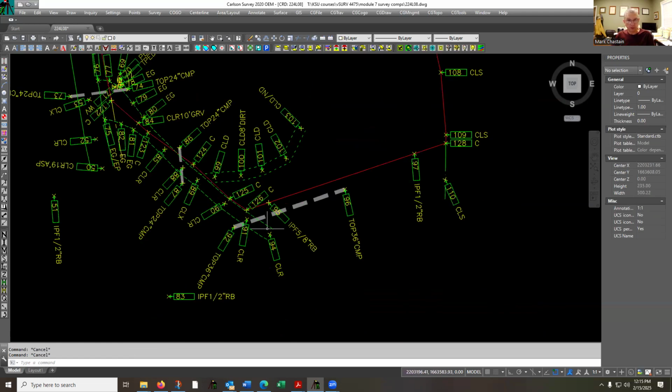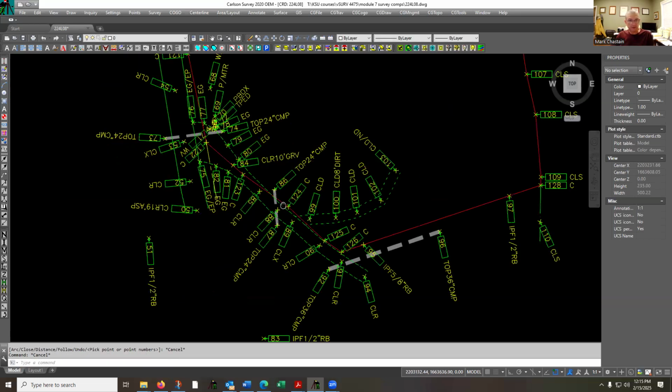Being that there was some question about the driveway and what's going on, there's this culvert where they piped some storm water. It's not very far from the property line, like 10 feet. So crew went ahead and located that just to keep everybody in proximity. There is no actual requirement to show power boxes, telephone pedestals, and water valves, which we have located up here. But it's a good idea to.